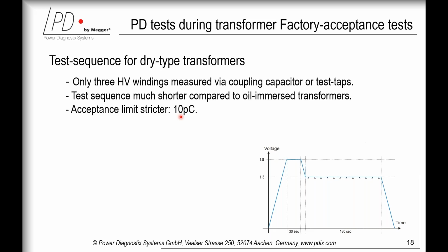One remark here: the IEEE refers to a length of 5 minutes for the first step for power transformers. It refers to a period long enough to ensure inception of PD, a possible PD within the transformer, with a recommended minimum of 10 minutes.